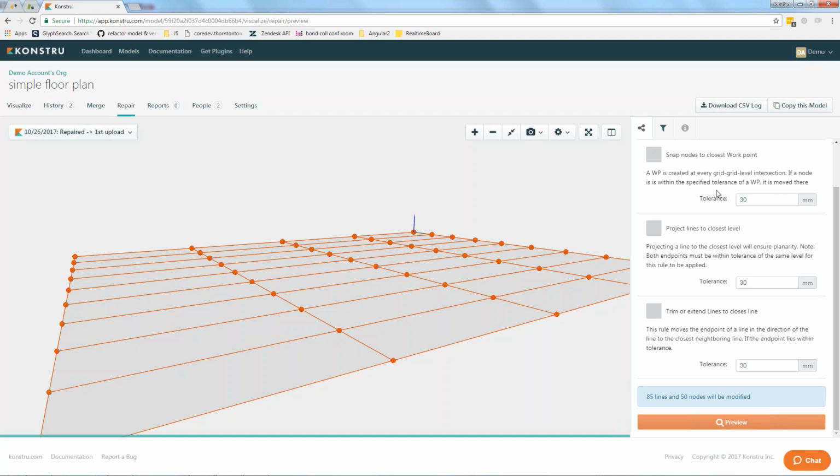The other thing, like Max said, we only just pushed this out a few days ago. This is not even a week old, and we are really looking for feedback. Somebody already mentioned that this is really good now for CSI-based models, but for RAM, for example, it is not that great yet, because what people wanted to see in RAM is the ability to automatically create levels and then to project those elements to the auto-created levels.